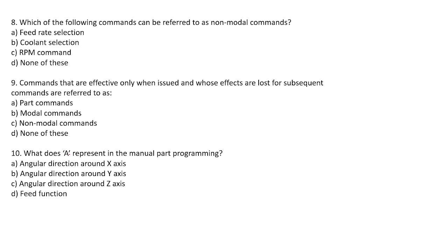So one is the fixed zero or fixed point, which is specified at some position of the machine table, and with respect to that all the tool locations are specified. Another one is the floating zero, where the operator sets the zero point at any convenient position of the machine table.